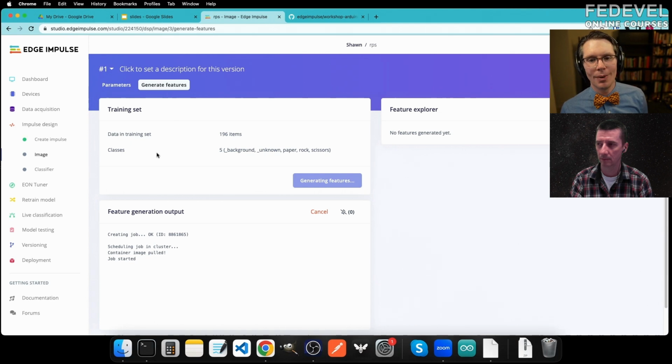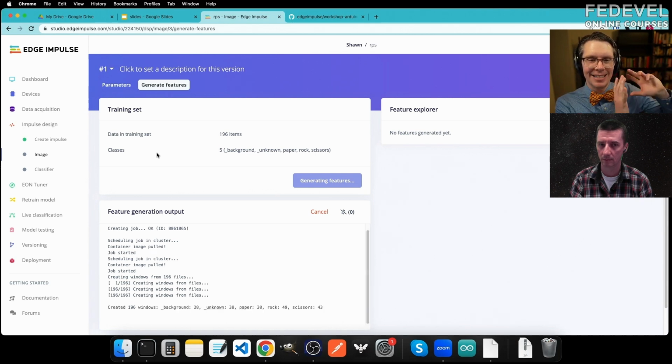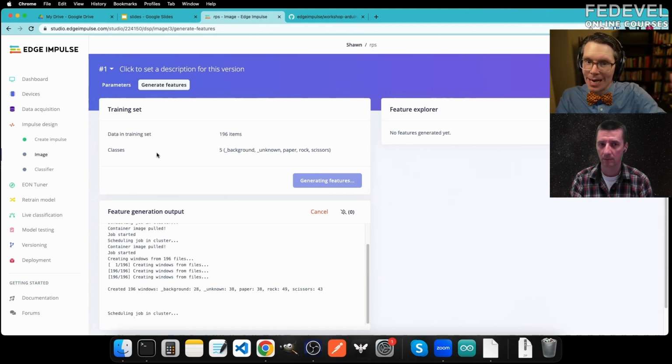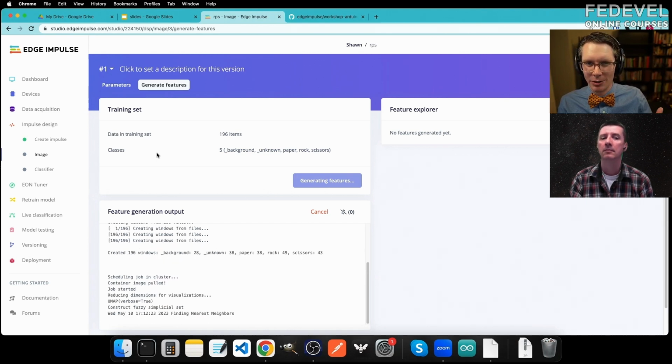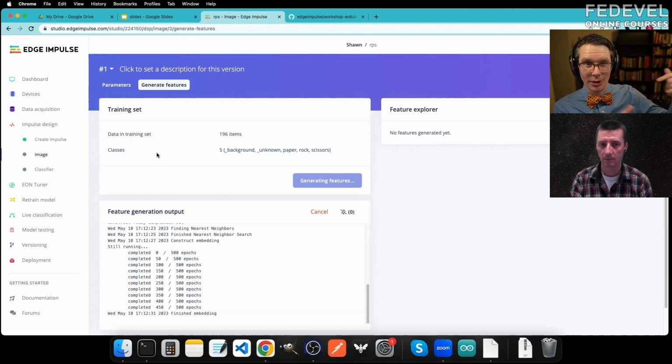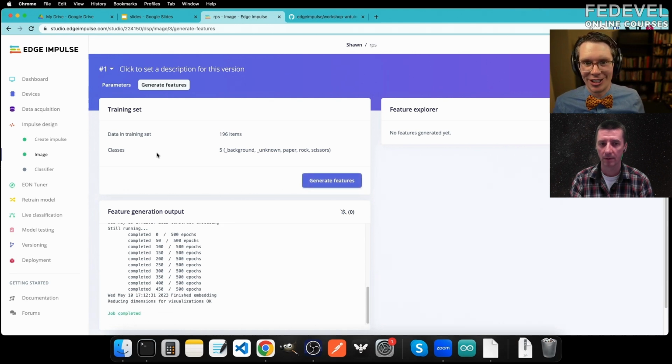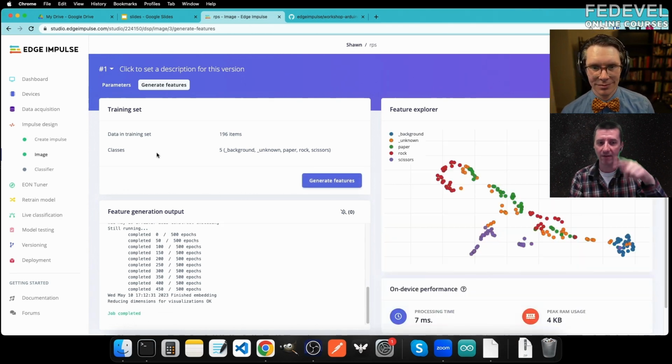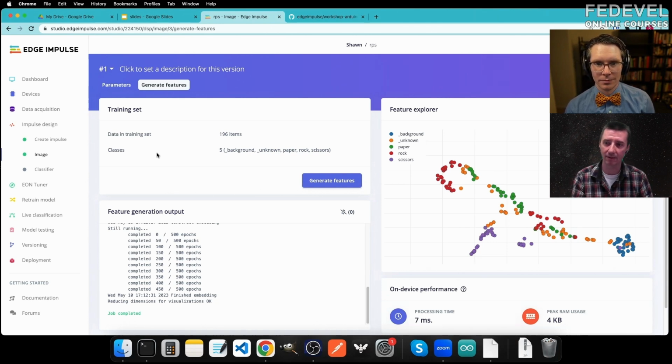Instead of this vision processing, you might have pre-processing that converts your data. One of the ways to think about keyword spotting is I take my waveform over time, use a fast Fourier transform or something, and make a spectrogram. Now that looks like an image. Most of the time, keyword spotting uses Mel frequency cepstral coefficients, which is like a spectrogram, and then it goes through another discrete cosine transform, and it creates these shapes, and then it does basically image classification on these shapes. So it doesn't really compare the waveform, but you may compare different kinds of calculations like spectrum, or maybe even more of them. Or only one of them? Yeah, it's usually spectral.